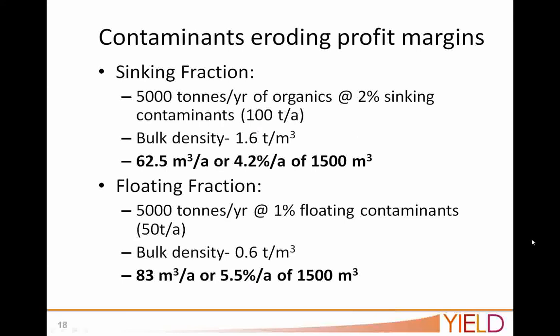So you think, oh, I have a volume. That's 100 tons of material. Just to start to get people thinking about quantifying. If you can quantify these potential risks, then you can begin to understand them a bit better. So let's look at their bulk density, and then how much. So if you have 62, say, well, is that really a lot? Well, there's a standard size digester we see around, a 1,500 cubic meter tank. Most common, there's larger, of course, but a lot of common size ones for about 500 kilowatts have two 1,500 cubic meter tanks, or one 2,000 or 2,500 cubic meter tank.